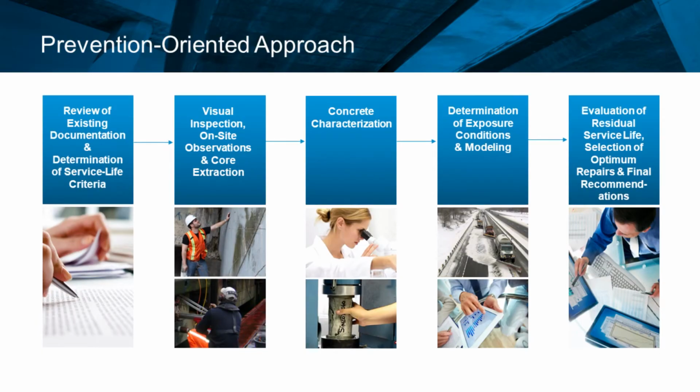And the other thing, NDE can be done also at this stage to document, for example, where the steel is located. So if you have a map of the concrete cover, you can evaluate when chlorides will reach that depth as a function of time. So you know exactly, or you have a good idea of where damage will occur on the bridge and the size of those repairs and when to expect them.